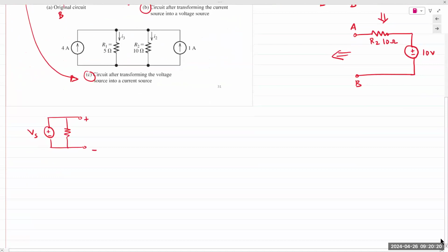So again, as I was saying, we have to represent the internal resistance of the voltage source that will consume some of the voltage itself. Now, real life voltage sources are designed with that consideration in mind. So if you set a voltage source to output 10 volts, internally, the circuit is built in such a way that the internal resistance should be as small as possible. But again, it can never actually be zero.